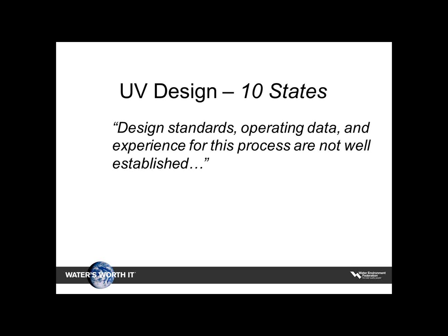1901. We're thinking it's probably a little bit longer, but that's one that goes in on the 10 States. That's the first opening paragraph in 10 States on UV. All they talk about is open channel design in UV and 10 States standards, and what their minimum requirements are: 30 millijoules per centimeter squared. Hey, now we know where Nevada and Colorado got their number from. That was a fallback right to 10 States standards on that.